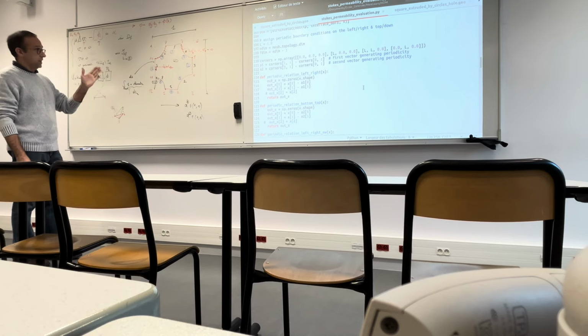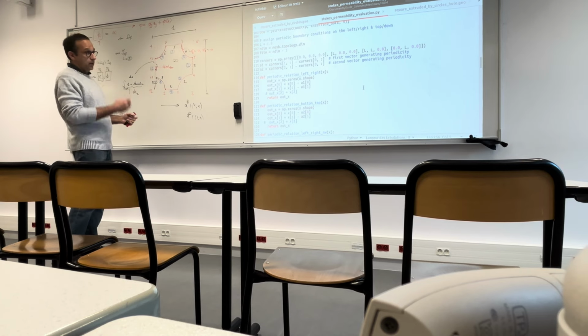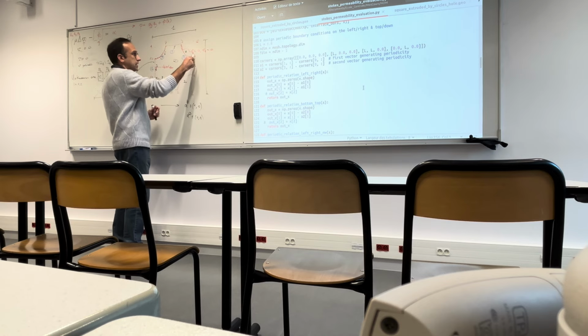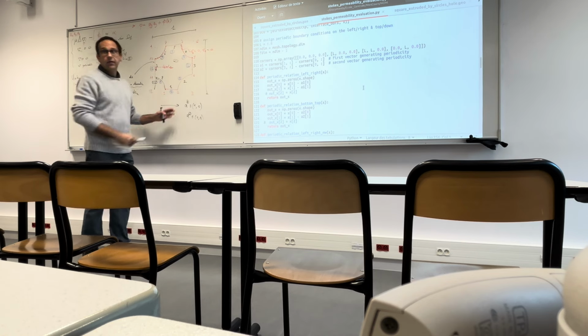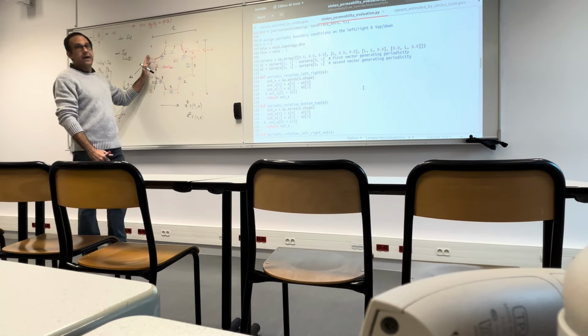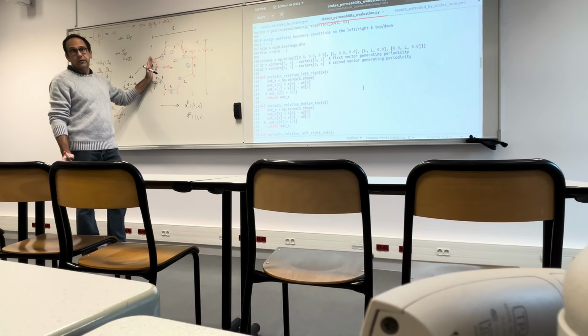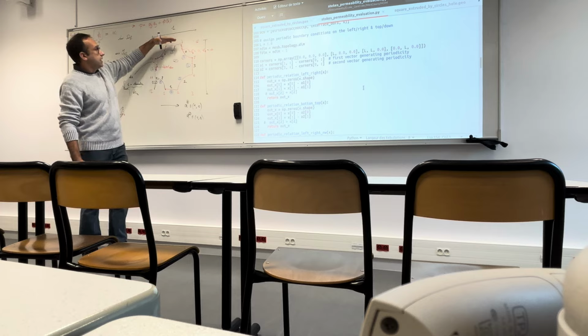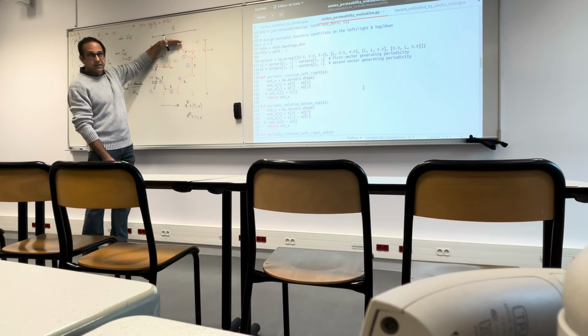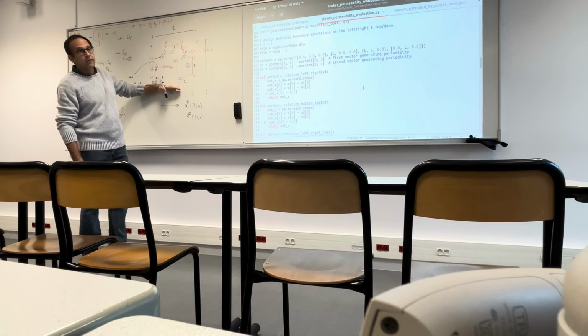So essentially what we are going to say is that whatever happens, for instance, on this part of the boundary, the same would be there. This is the periodicity condition. Whatever happens here in terms of unknowns, the same would happen there.